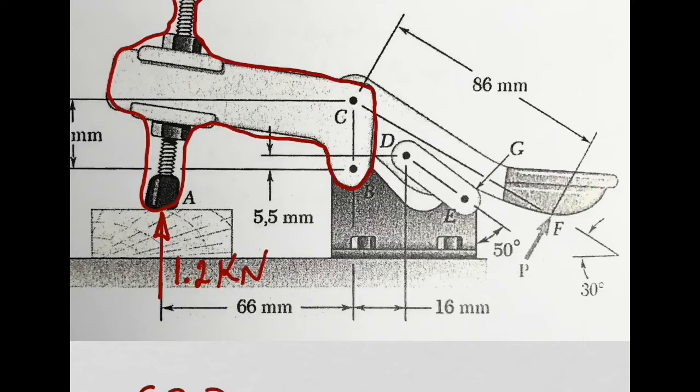Now look at this. Points C and B, they are hinges. If I try to move point C in the horizontal direction, do you think that hinge will allow that movement or not? No. So if that movement is not allowed, there is a constraint or a force there, a reaction that is blocking that movement, and I need to include that reaction.